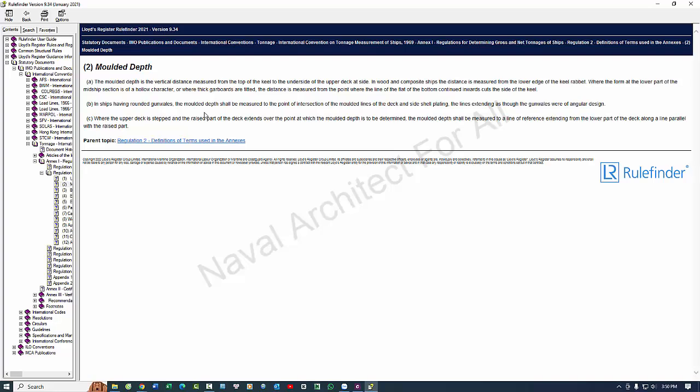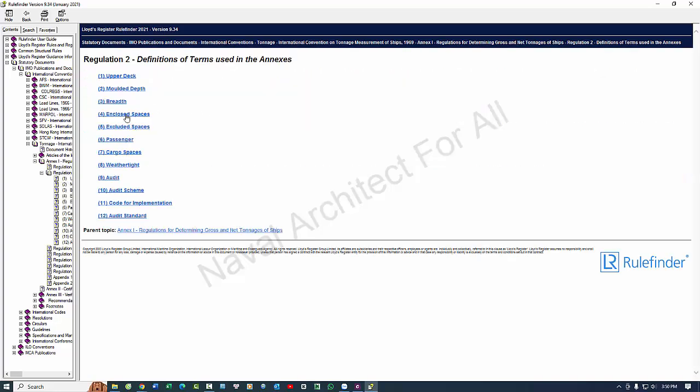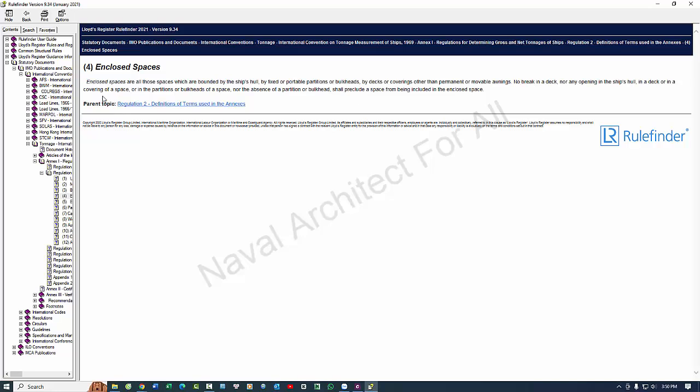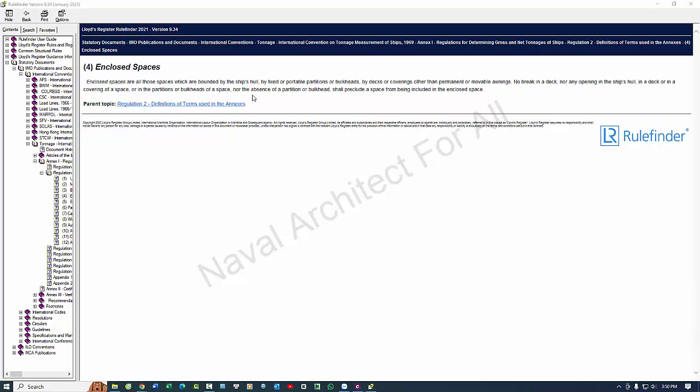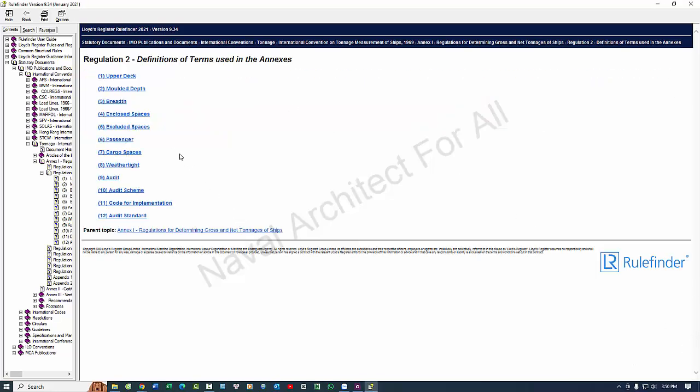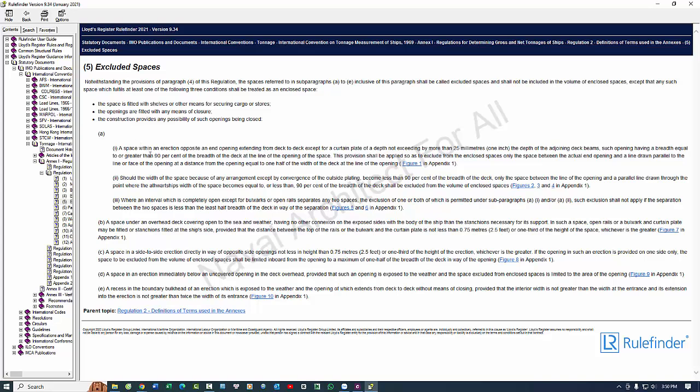4. Lightship or lightweight tonnage, the weight of the ship itself without any cargo, fuel, passengers, or crew. This is important for stability and structural integrity assessments. 5. Displacement tonnage, the total weight of the vessel when it is floating, equivalent to the weight of the water it displaces. This is used for assessing the vessel's stability and structural strength.